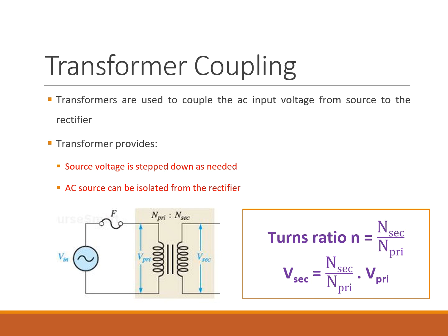And then where electrical isolation is concerned, there's no direct wire connection between the primary, which is the input, and the secondary, which is the output. Because you have no physical direct wire, this protects the rest of the circuit from surges or faults in the power line. Another important concept to understand is the turns ratio when we're talking about transformers.